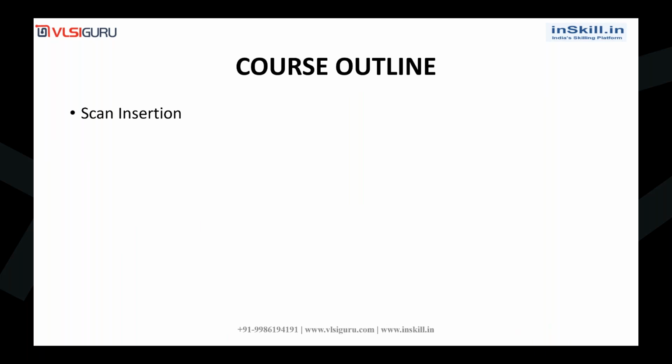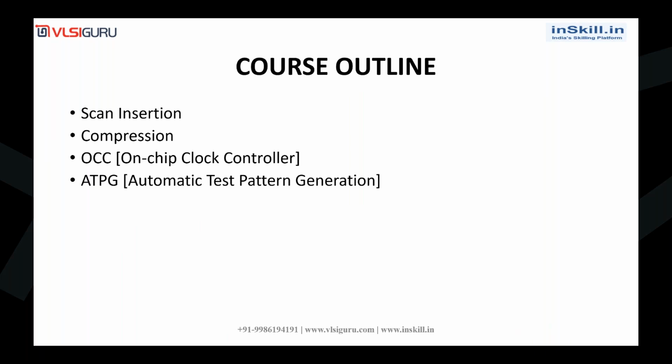So, the first one is scan insertion. We'll first start with scan insertion. Then we will have scan compression, and after that we have on-chip clock controller OCC, then automatic test pattern generation ATPG, then simulations, then JTAG, Joint Test Action Group. This JTAG is the IEEE 1149.1 standard.